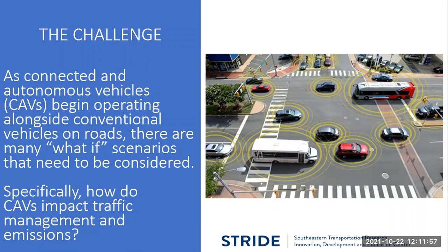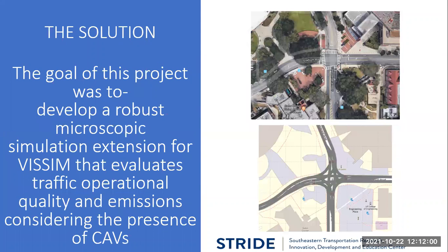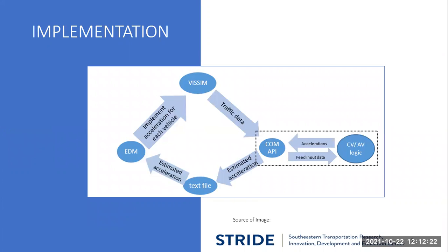So our solution to this challenge was to come up with a microscopic simulation extension for VISSIM, VISSIM being the most used, commercial, widely accepted simulator, to develop an extension that evaluates traffic operational quality as well as emissions in the presence of CAVs. To implement this solution, we use two key components of VISSIM: the COM application programming interface and the external driver model.